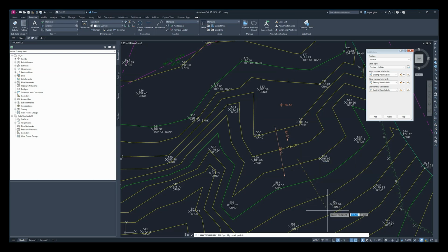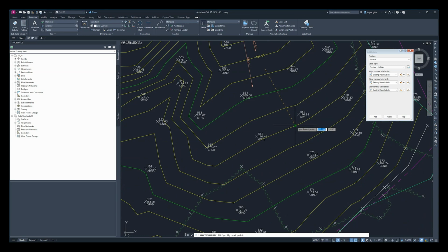So click that. You're going to see it asks you to select a second point. Let's go past our first major elevation and just a little bit past our second major elevation, clicking close to that 571 point. Once that's clicked, we can hit Enter to end the process. And we see along that line that we just created, we have elevations at every single contour it crossed.